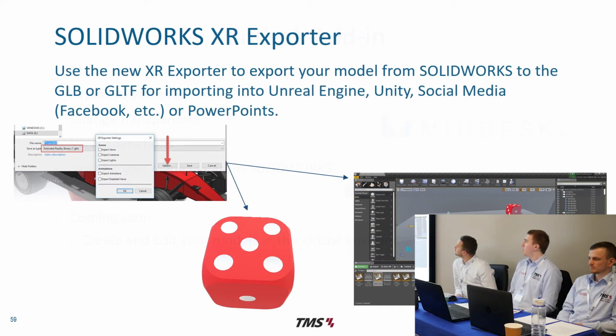Talking about that GLTF format that I mentioned, in SOLIDWORKS 2019 there was a beta option to export models to either the GLB or the GLTF format using the SOLIDWORKS XR Exporter. That's still there in SOLIDWORKS 2020, and also it's included in Visualize to get even more high looking images and renders. But where can you actually use those outputs? If you want to go to the top end, you can export them to programs such as Unreal Engine or Unity. And we've got an example of that out on the street area out there, where you can take models from SOLIDWORKS and export them into Unreal.